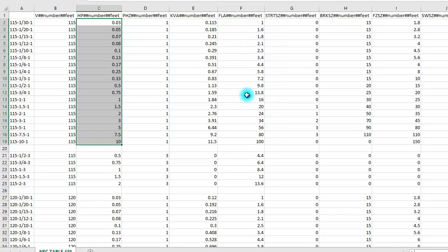So now we're able to start calculating full load amps, MCA, MOCP, and ultimately apparent load before a selection is even completed. And electrical has the full ability to override any of the numbers, or they can choose to use the mechanical values to start.